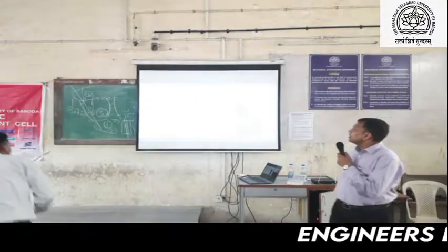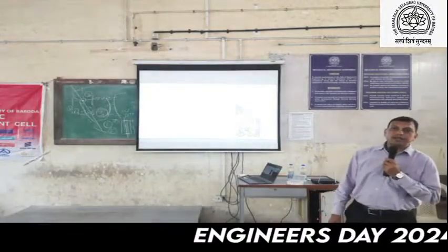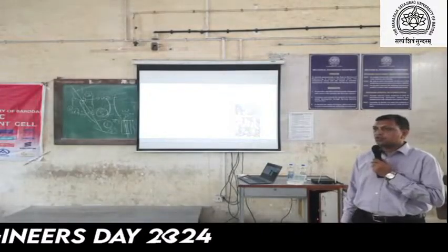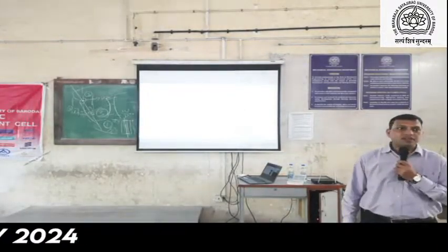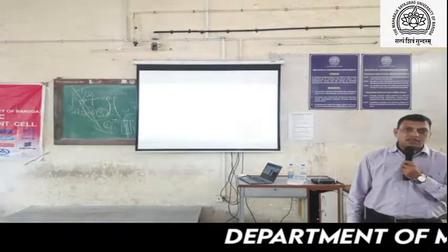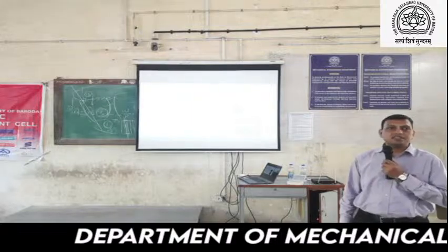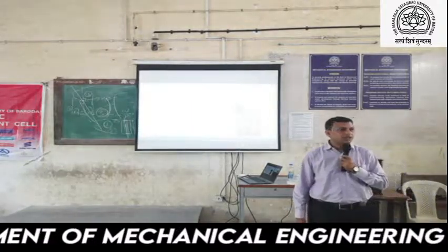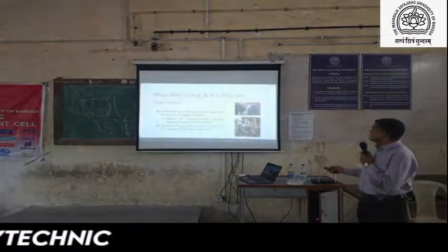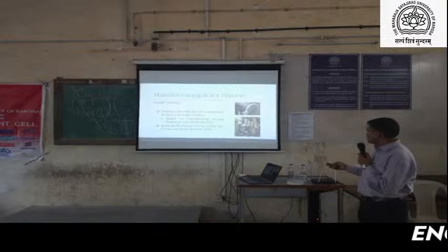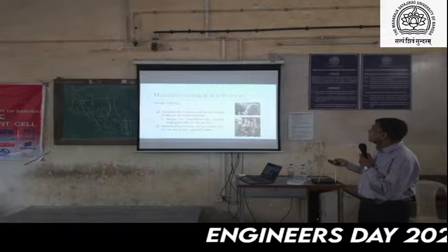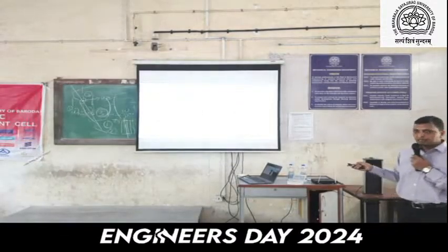So the first part is the rough turning. If we have the raw material as a round part, we start to manufacture the pinion. So the first process is the rough cutting. That will shape the particular shape which we require. Some allowances should be considered related to heat treatment and distortions. You can see in this image that the round bar is placed and this is the base cutting.